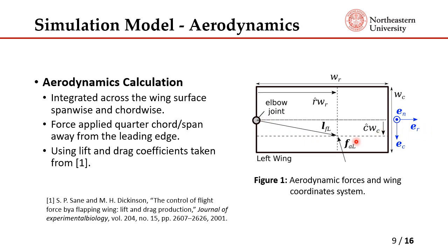We have both span-wise and chord-wise integration. In this case, we integrate about the span and the surface about the chord, and then the force itself is applied a quarter chord away from the leading edge. We also do another integration across the span, because there's a possibility of this edge being the leading edge as well, due to how the flapping works. So this is done to take that into account. The lift and drag coefficients are taken from Dickinson, as I mentioned earlier.